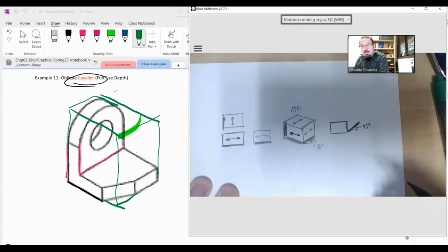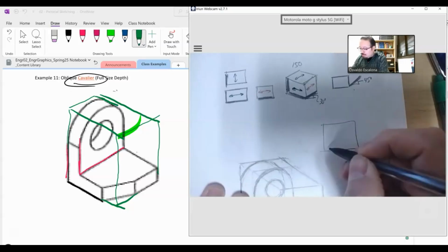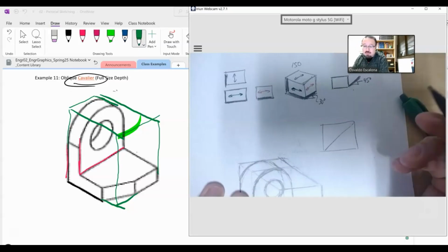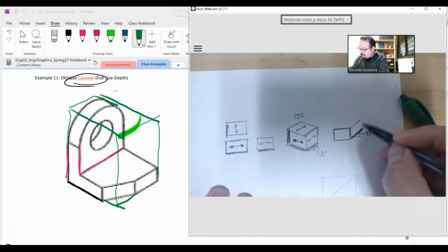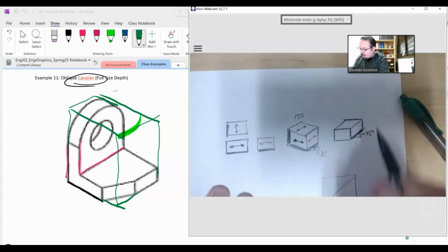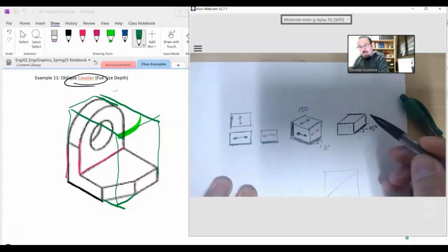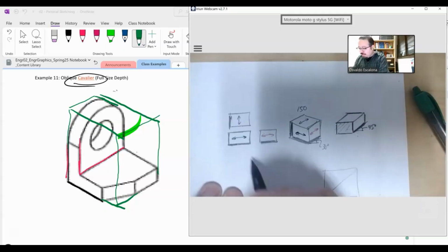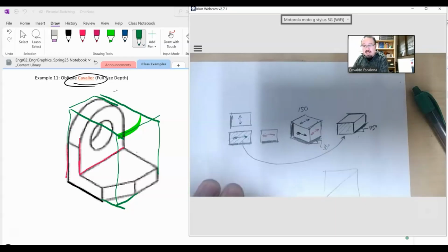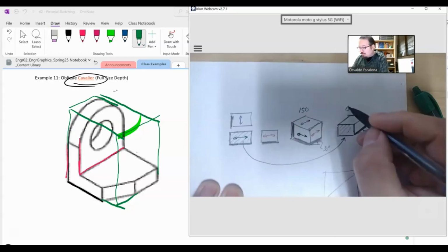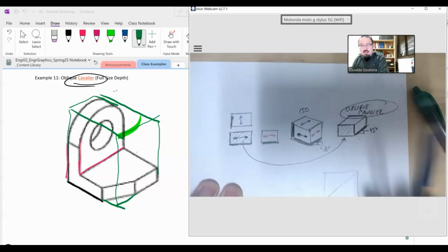How do I do a 45 degrees in squares? When you got a square, and if you go from corner to corner on one square, it will take you 45 degrees. You don't know how to do 45. When you have that distance, then you can do the other 45s, and boom. Hopefully that makes sense. Whatever you see here and any parallel behind it will be a true size. So the same shape that you see here should be the same shape that you see there. And everything that is parallel. Oblique, cavalier. Which I believe is what you guys are doing.